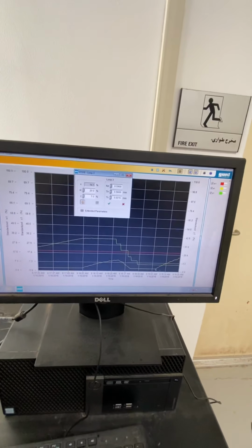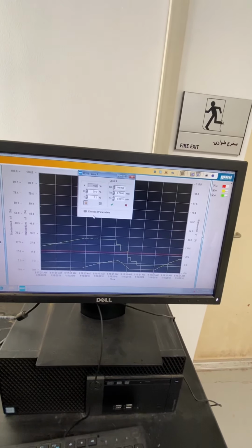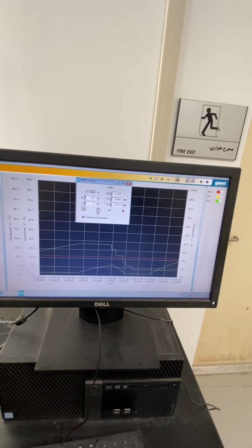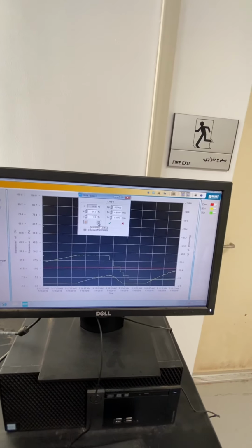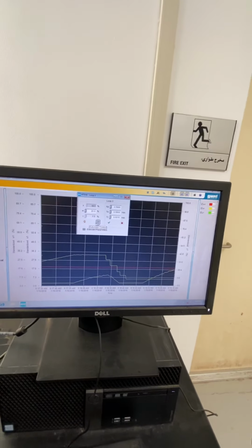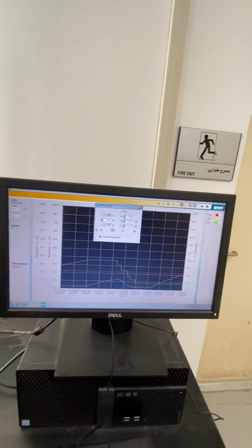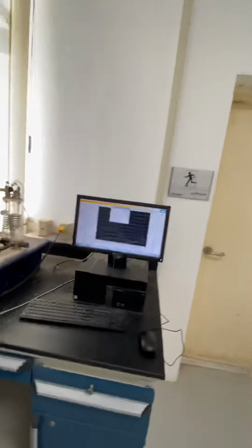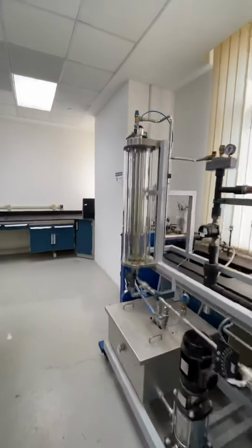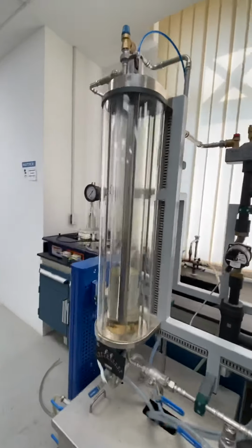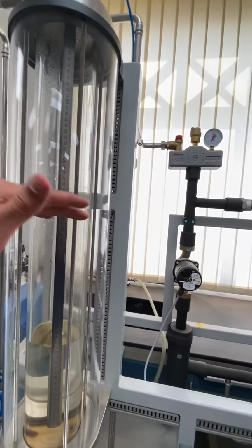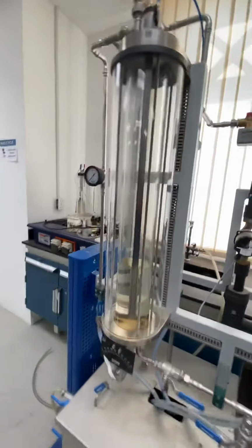The process trend actually is a very powerful tool. It doesn't just show you the history of a process. It would rather tell you if there is a problem or unusual behavior in your process, guys. So as an example, you work in a process like this process, guys. You have a tank and you are used to noticing that at, let's say, 40% level, the output signal is 10%.